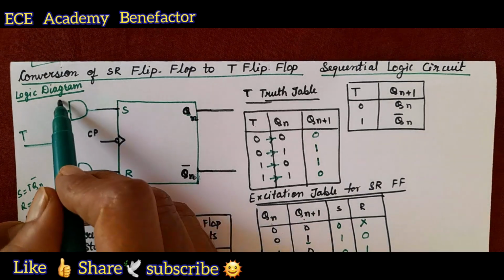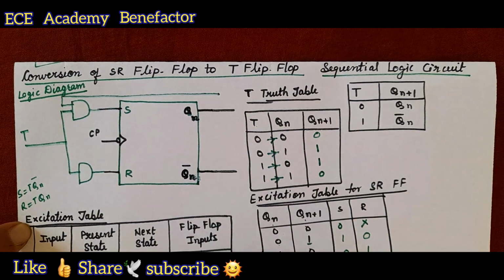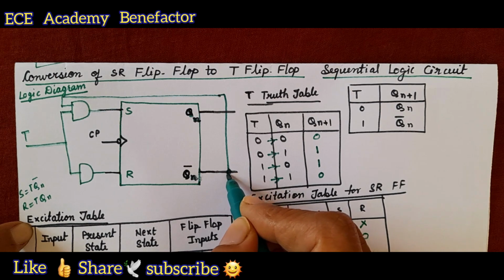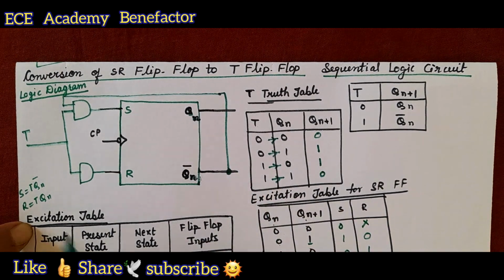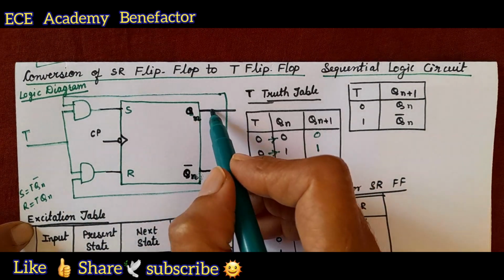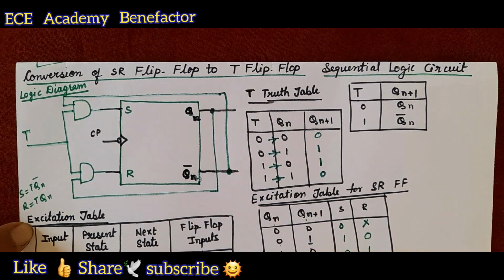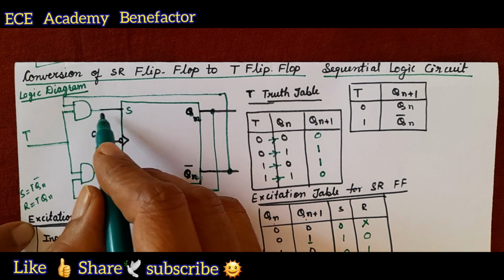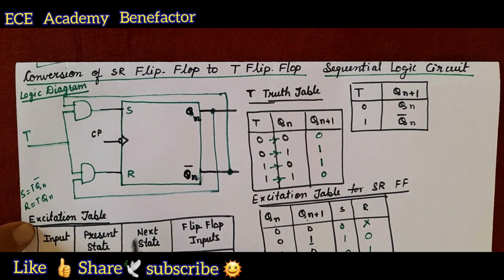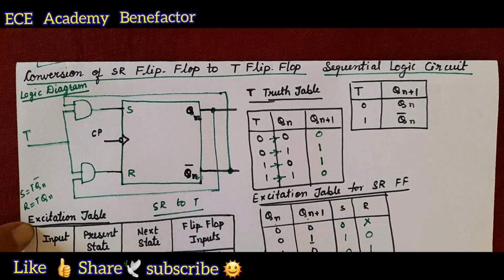Where is S going? S is going to Qn bar. As you connect here, darken this point. Now this R is going to Qn. Darken this point and connect to R in this way. So S is connected to T Qn bar and R is connected to T Qn. So in this way we can convert SR to T flip-flop.